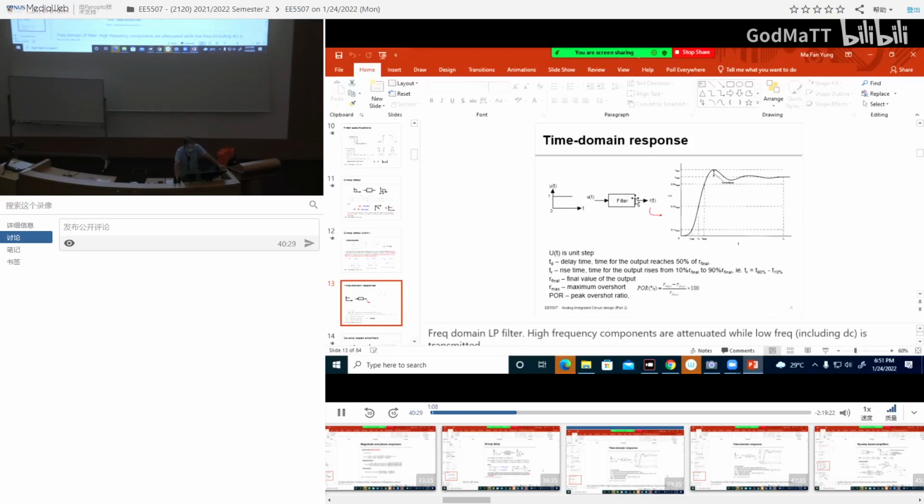So we are assuming here this is a low pass filter. We know for a low pass filter, it will pass what? Low frequency, including DC, right? DC is 0 frequency. So the unit step over here, the value is 0, so here all will be 0. When the time is very big, far away, it is DC of 1. So here, far away, also DC of 1.